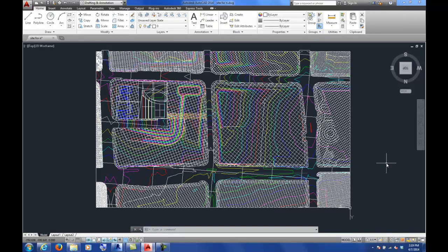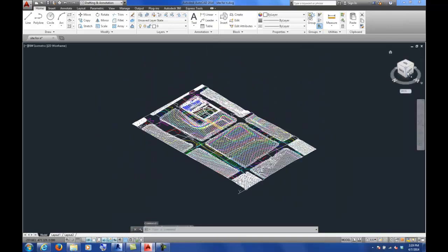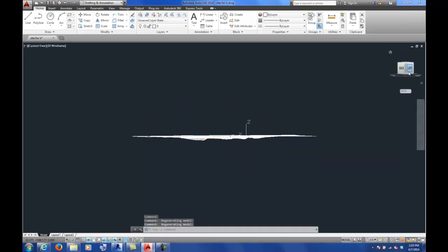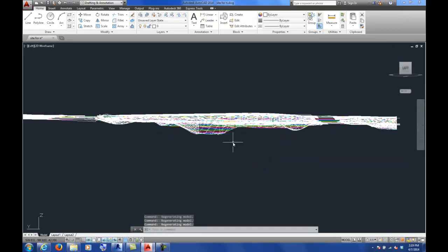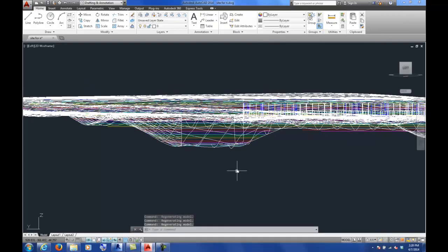The important thing about trying to bring this into Revit is that if I were to look at this DWG file, which I've got open in AutoCAD, in an elevation view, I should be able to have not a straight line. What you see there is all the colored lines up on the screen, those are all the contour lines, and they're actually at the height of 734 in the z-axis, or 733 and so on. If you get a file where you turn to the elevation view, like I just did in AutoCAD, and this is all one complete straight line, what we're about to do in Revit won't work.